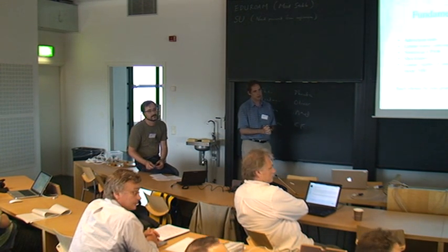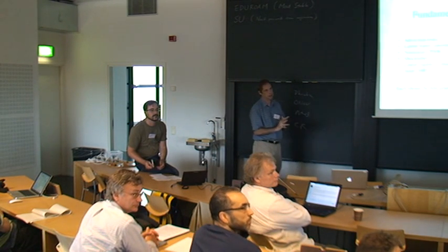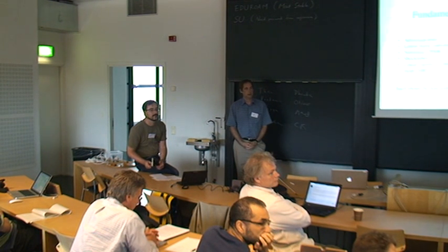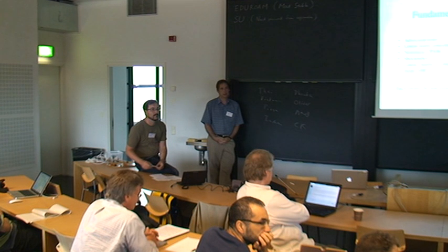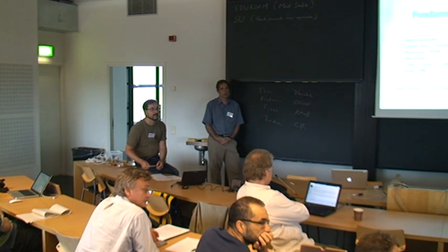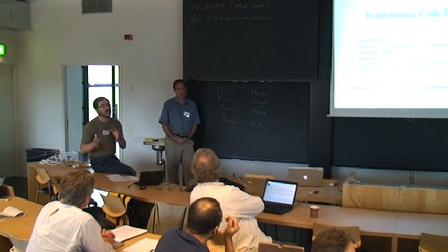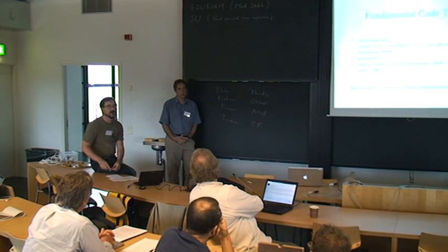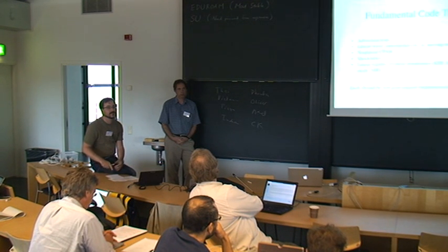The difference is, and I'll show in my talk tomorrow, running that with SPH, and it is interesting to see, because it will eventually blow up in any code, something will perturb it, so you're walking right on a knife edge, and you can get quite a large contrast between different discretizations of how long it goes before something does blow up. But it's also a common wisdom that you should never actually do science with that kind of accurate thing. The more accurate your code is, the more prone it is also to amplifying your grid noise and making it less robust.